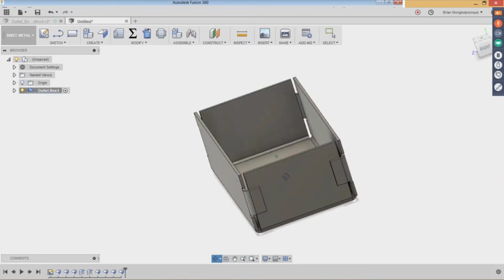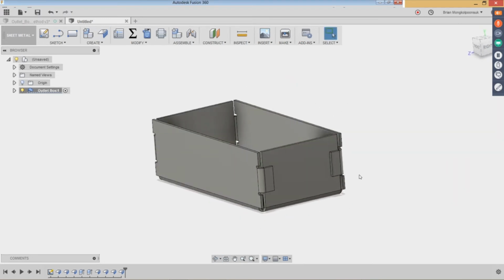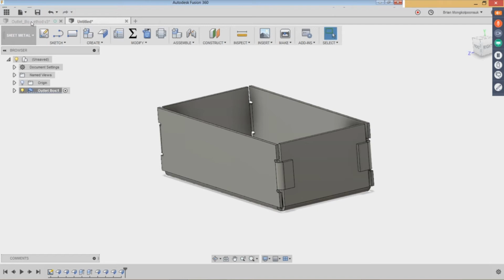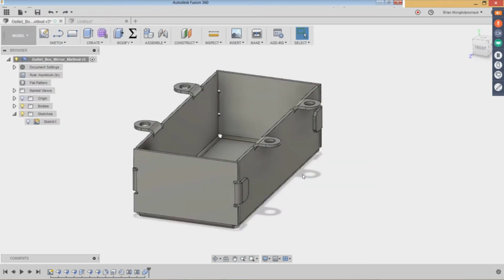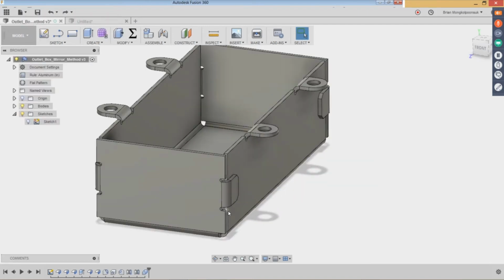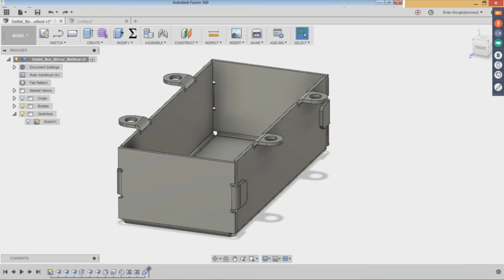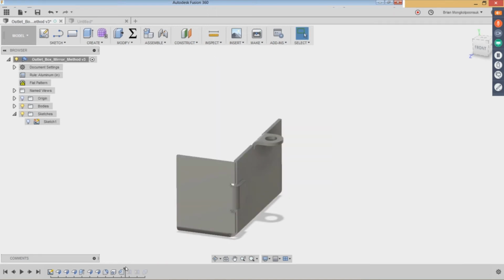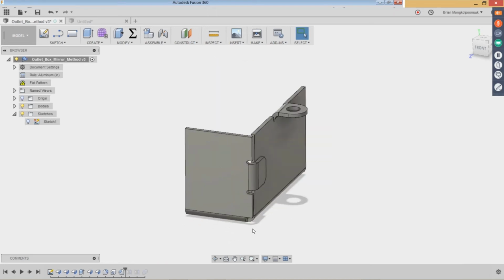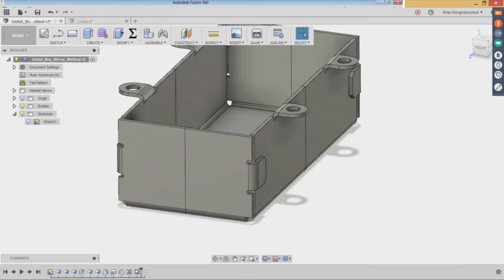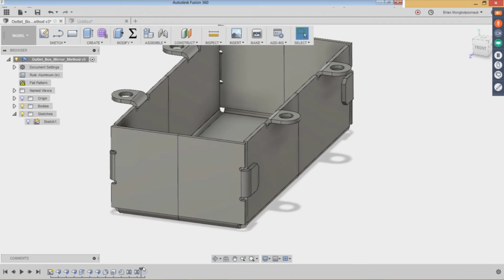Okay, so now we have most of the box created. Notice this box earlier, I actually created it a different method. I pulled this design history bar down here. Notice how I just created a corner of this, and then I did 2 mirror techniques to create that part, as well as a combined technique.